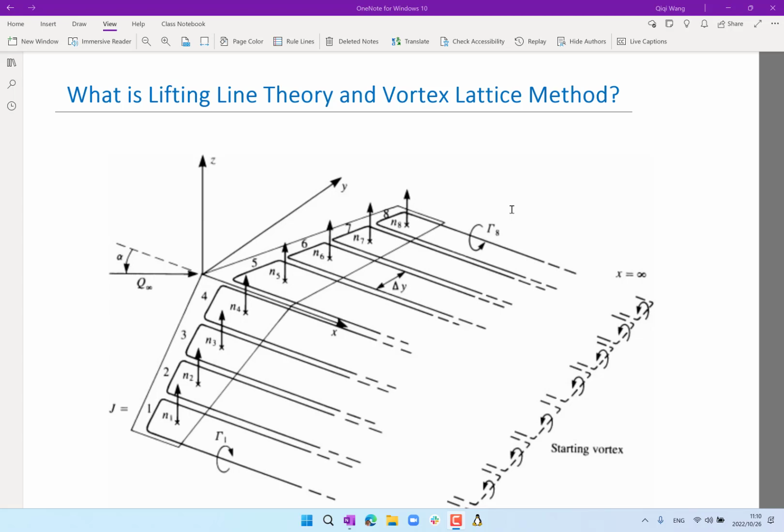So this is, I would say, the most simple way of computing the flow in 3-dimensional bodies. There are more advanced ways that take into consideration not only how strong the vortex coming out of every section is, but also how these vortices are actually going to move in three-dimensional space. Remember, this model assumes that the vortex coming out of the wingtip and in between these sections just goes straight downstream to infinity.